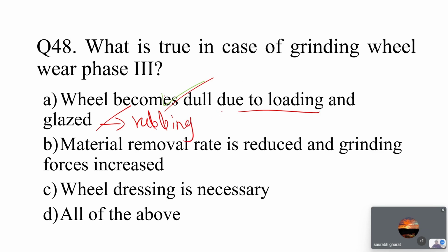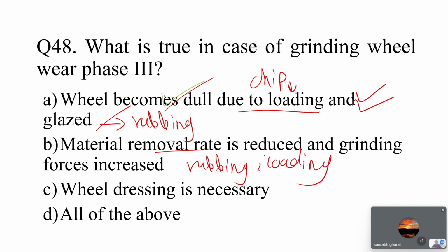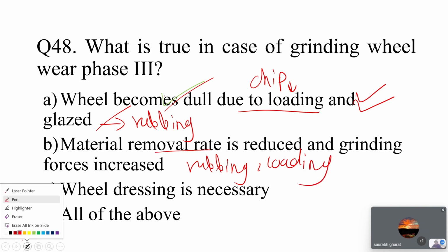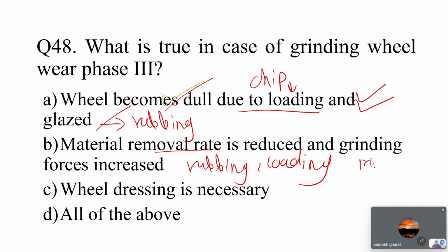Material removal rate is reduced and grinding forces increase, due to the rubbing action and the loading action. Your MRR will be reduced and the grinding forces will increase. So this is again true.